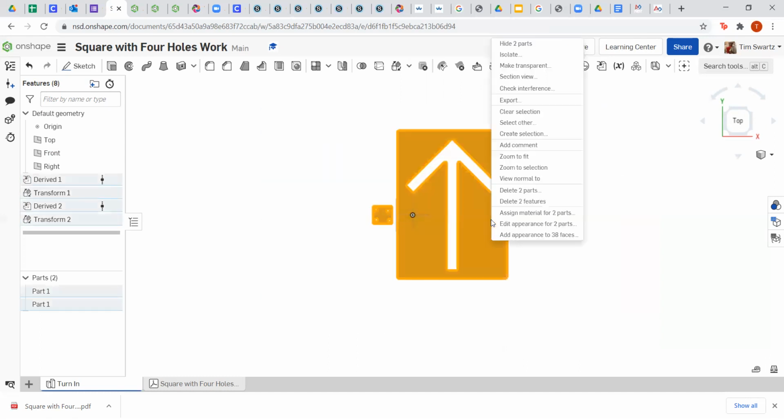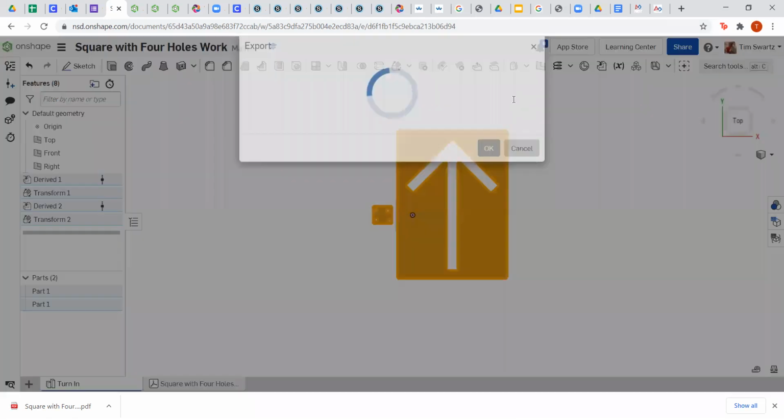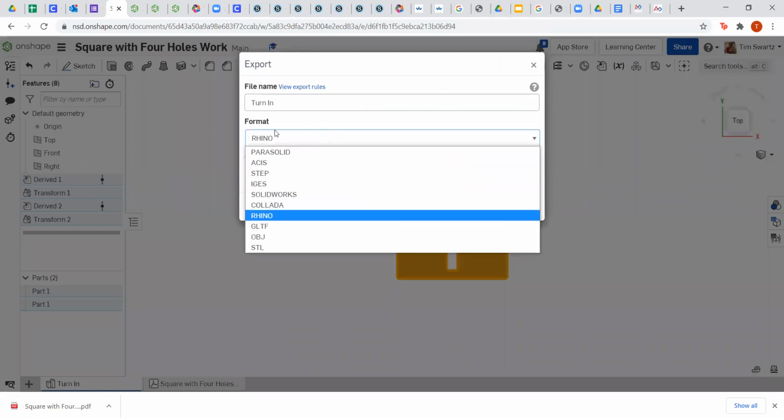And then once we have all of our projects imported by our students, we can actually select everything. We can right click and we can do export. And from that export, you can have a bunch of files here. So if these are all going to be 3D printed, you can export them as STLs. But I will remind you that if you do an STL, all the objects are going to be in one STL. So that would be one print. You can't separate it in your slicer after that. So you could batch them from here, or you could just do individual STLs for the files.